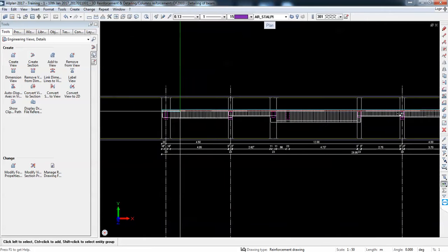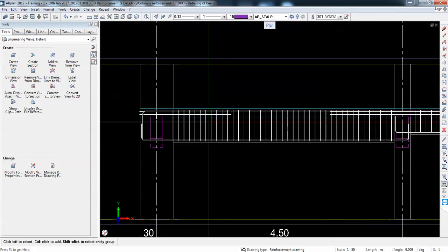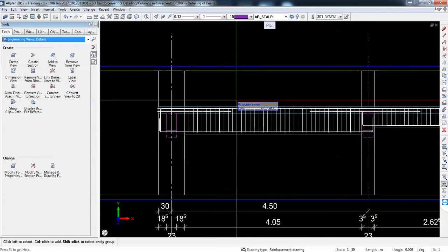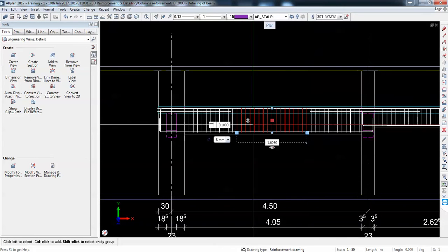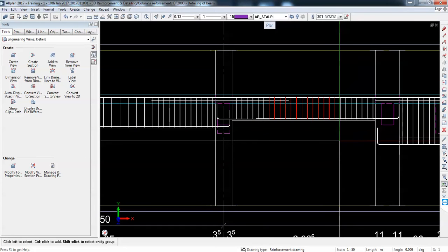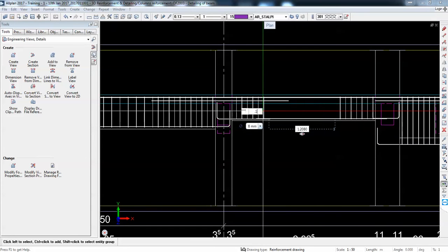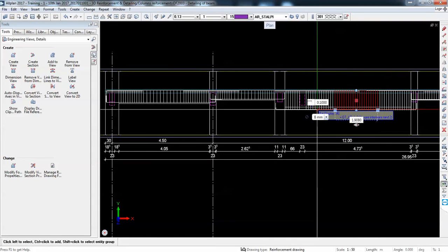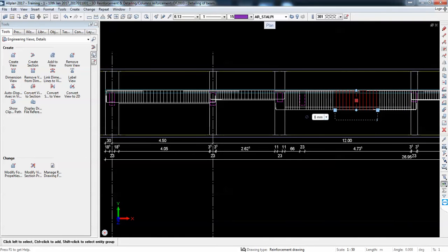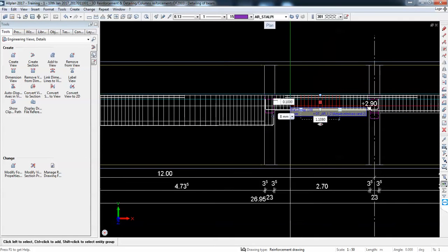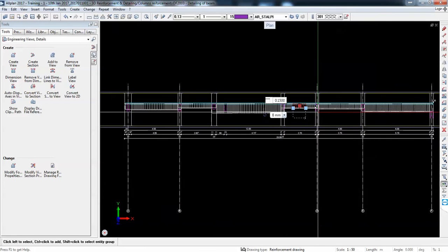Then, what I'm going to do is sort the stirrups. So the stirrups should have some variation, of course. I can do it here. For instance, here, as we discussed yesterday, we can have 0.15, and on other areas to have less. So exactly the same workflow we did yesterday for the column can be applied to the beam. So you decide which are the critical areas, and then even in the detailing stage decide where we should change the stirrups at a bigger pace.